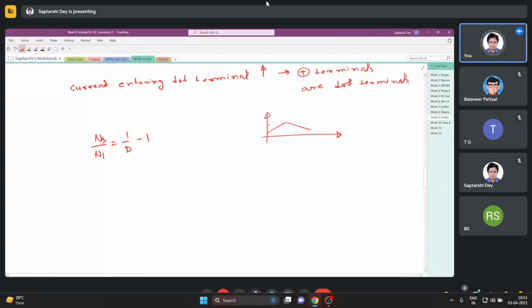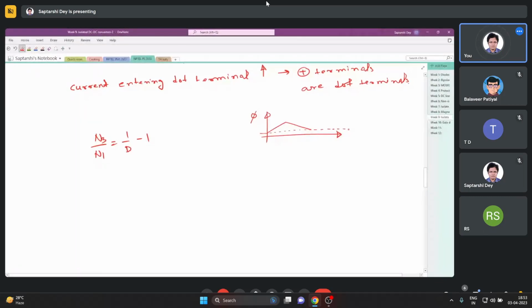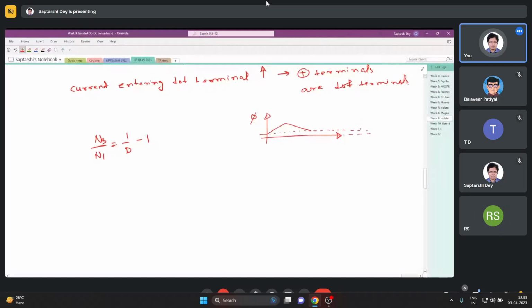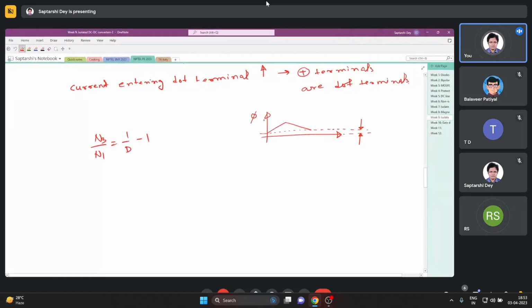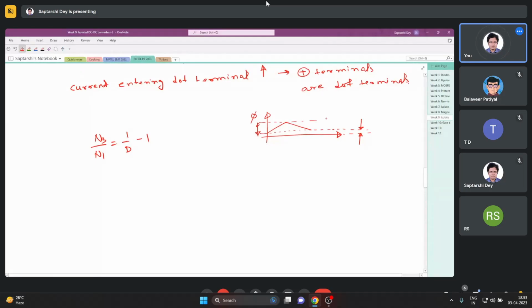No. Say you have a flux waveform like this in a flyback converter core, then this much flux is always stored in the core. When you are closing the primary switch, this much energy is stored in the core extra. When you open the switch, exactly that much energy is sent back to the load. So the thing is, this much energy unnecessarily gets stored. So why design it here? Design it here.